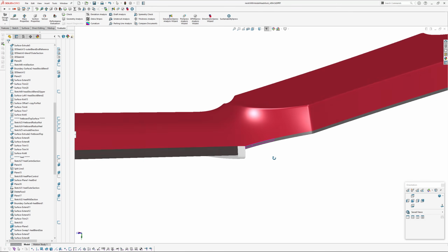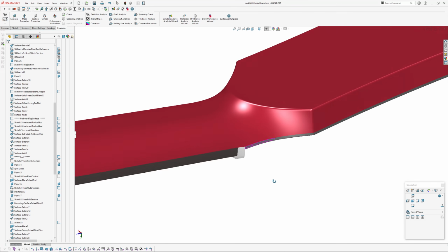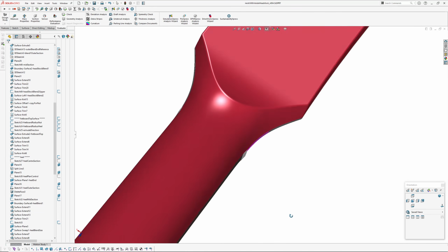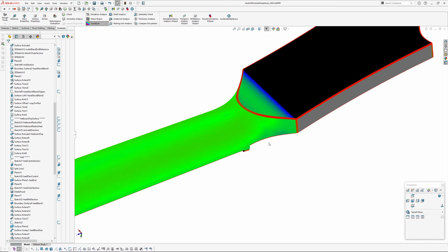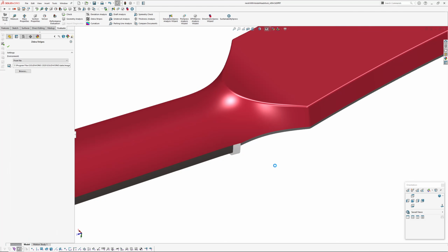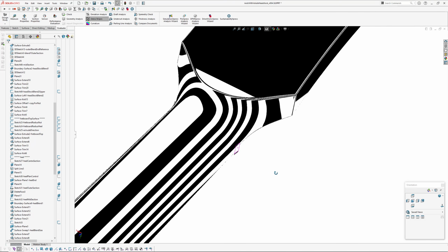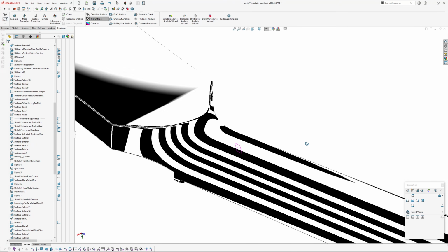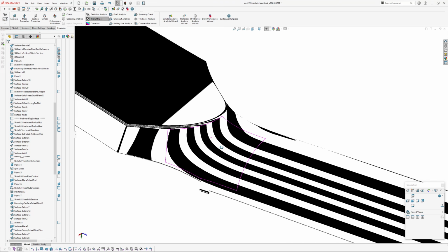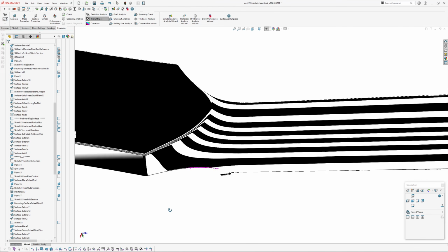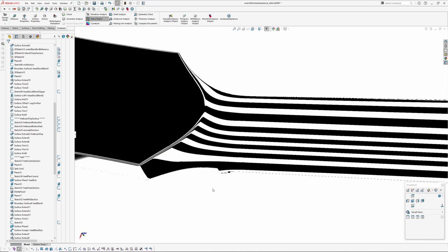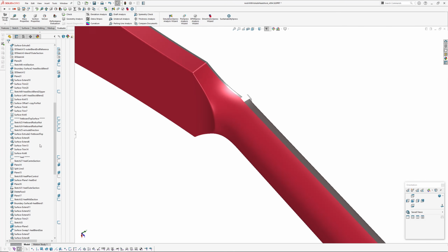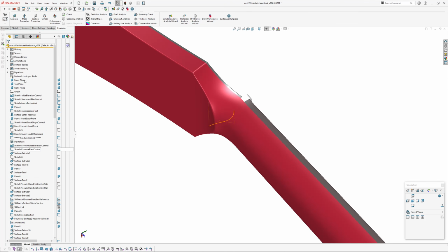So I've got an overbuilt surface in there, plus another little patch on the end, and then that's been mirrored around. But the result's fairly good. Quite happy with it, and it's tweakable as well. And the fillets that went on afterwards are just straight fillets, curvature continuous fillets, but just looking at the main zebra stripes up through. Okay, I'm going to roll back now and just explain how I made this.